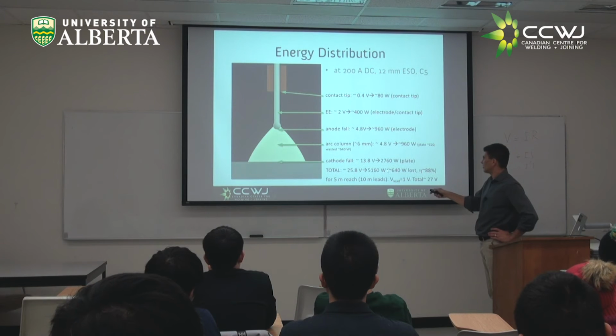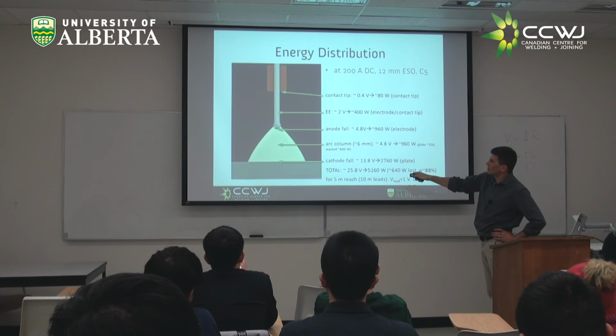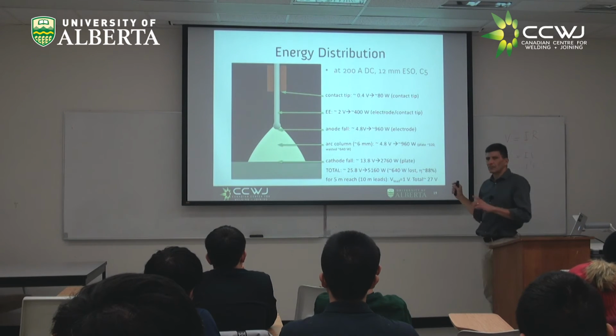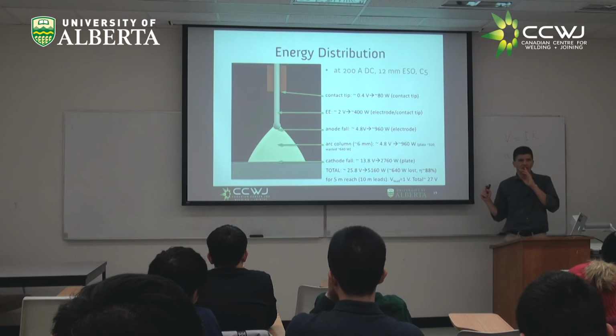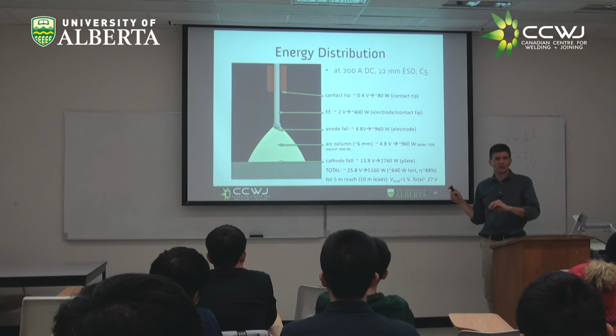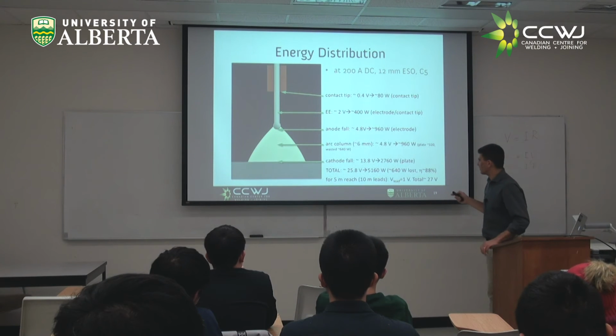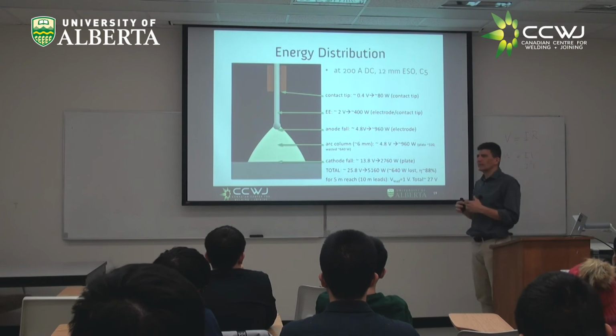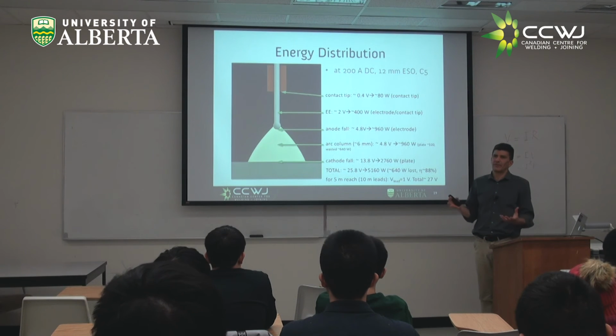All these watts here, of which 640 are lost, because whatever energy I put in the wire comes back into the melt, right? The only thing that really goes wasted is these 640 that are 2/3 of the arc. And this is something that Mitch mentioned last week on Tuesday, right? You can start making some sort of an efficiency assessment.